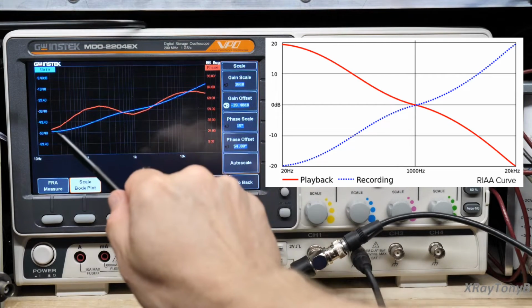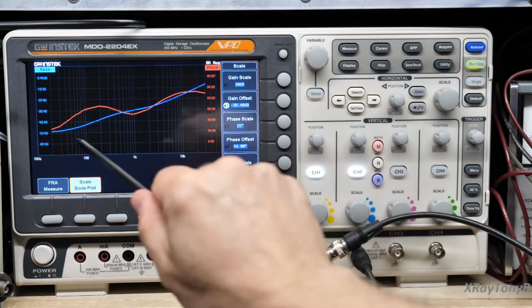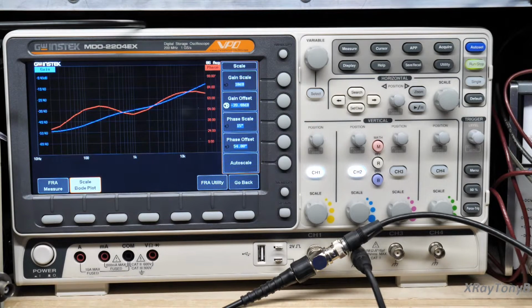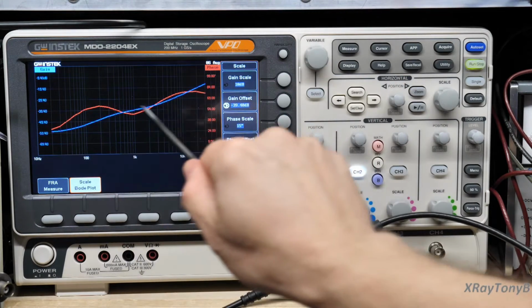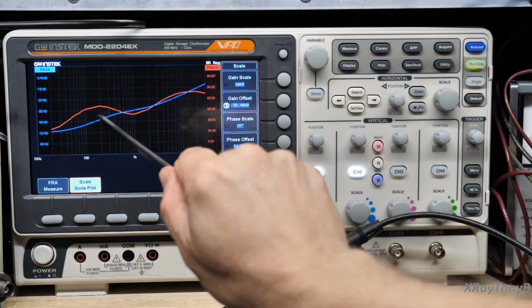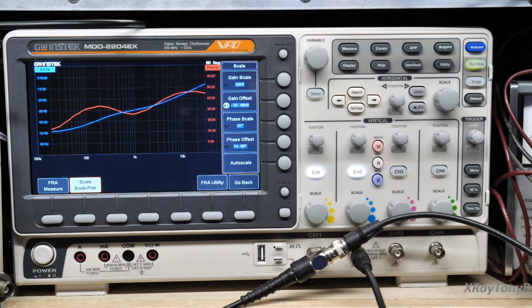And if you notice, this is not a bad looking RIAA curve. But notice during that whole process what the phase shift is doing. And that's because of all of the reactive components in there. That's because of the capacitors that are in there that are affecting this curve. So there's reactance taking place, is what that's telling you, to make these attenuations and boosts take place. I don't know if that makes sense or not, but that's an RIAA curve you're looking at of a phono stage.